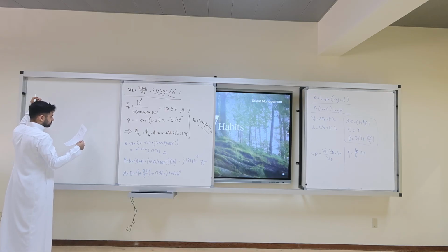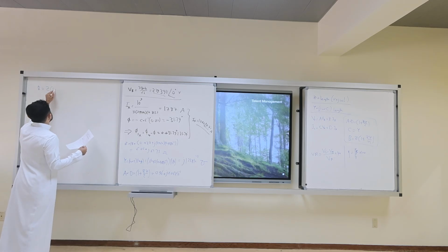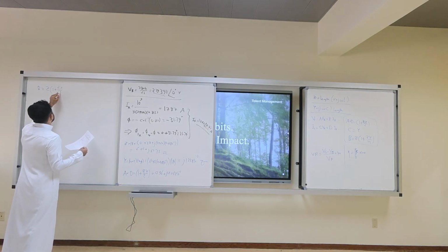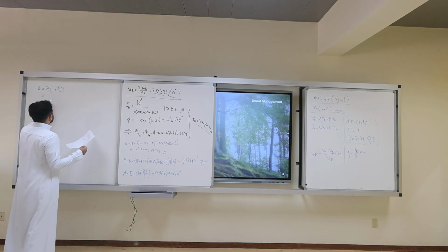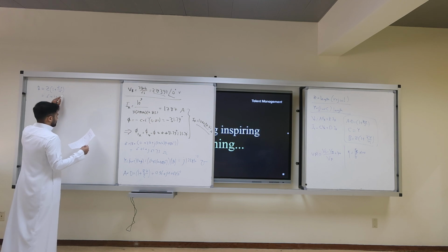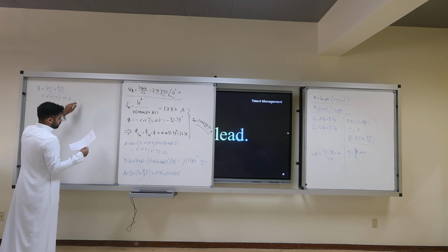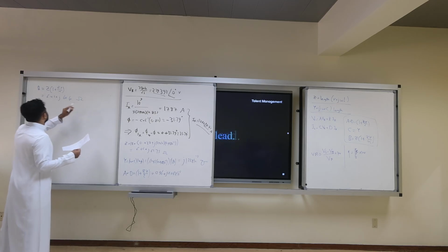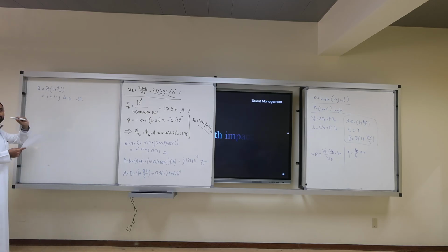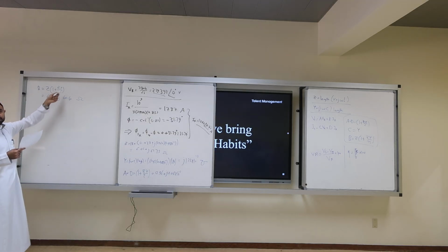B equals Z times 1 plus ZY over 4, which will be equal to 6.41 plus j times 60.60, and it has a unit of ohm. Why? Because Z times 1 is ohm. 1 plus ZY over 4 is unitless, Z times unitless is ohm.